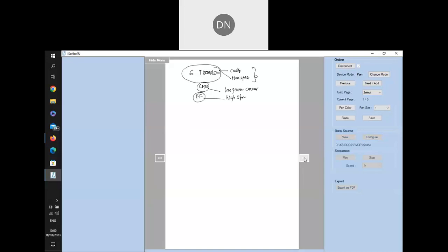So if somebody asks what the features of SRAM are, these are the features. Since it is made up of flip-flops, which work at the speed of the processor, they are able to supply the data within a single clock cycle. You can complete the operation in a single clock cycle, bringing the data from the memory and putting it into the register. Since flip-flops are used, the speed of the memory cell is very high.